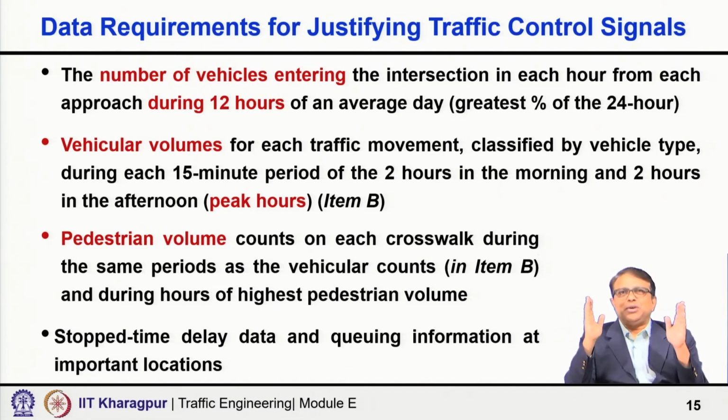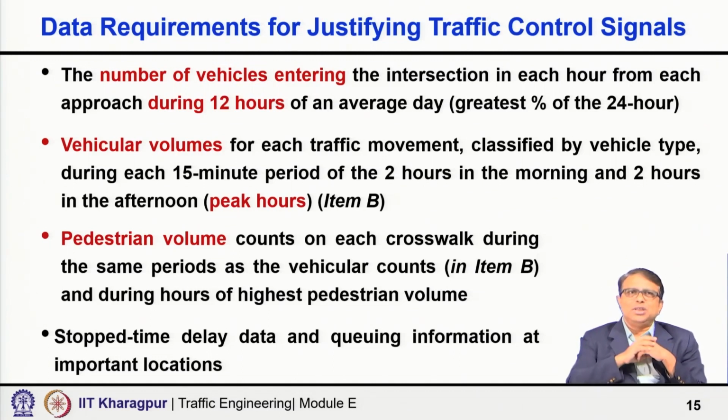So, the 12 hours where the traffic volume is maximum. For the 12-hour traffic volume study, we need vehicular volume for each traffic movement classified by vehicle type during each 15-minute period of the 2 hours in the morning peak and 2 hours in the evening peak.